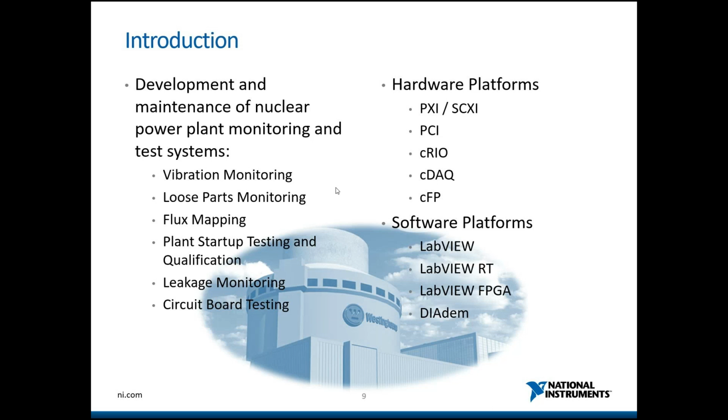I don't know how many of you know, but back before Fukushima, there was this thing called the nuclear renaissance. They were building new plants. And they put everything in place, and when they started up, it's called a pressurized water reactor, so it's got really hot, super pressurized water running through it. And if you're a mechanical person, you know that when things get hot, they expand. And so the pipes all expand and move. And so we had a bunch of CompactRIOs, on the order of 100 or so, spread out throughout the plant with various sensors to measure parameters on all these pipes, to measure the slope and various things that needed to be verified to make sure that they hadn't moved too much so that they were still in spec.